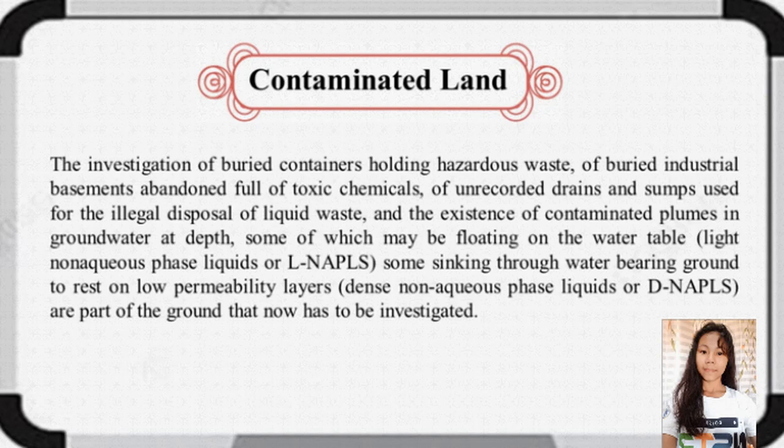In this area, geophysical methods are used to help define and quantify these conditions, and their applicability is still being realized. Many techniques in this area can be used. Could be metal detectors for revealing buried metal containers, electrical resistivity for detecting changes in water quality, and also ground penetrating radar for locating trenches in which drains may be located.